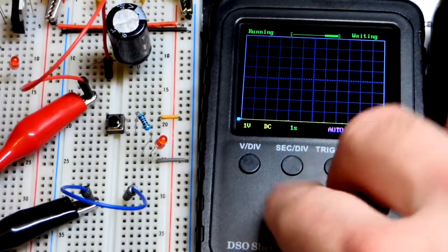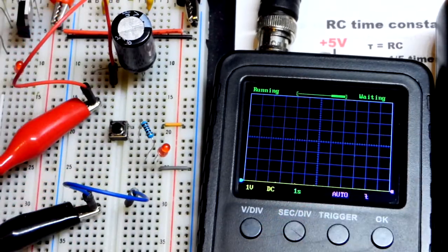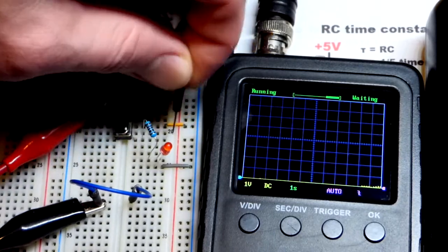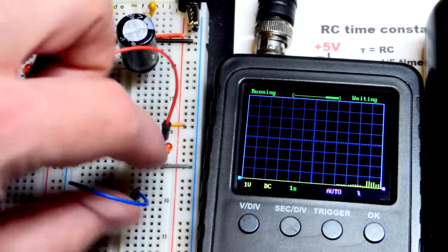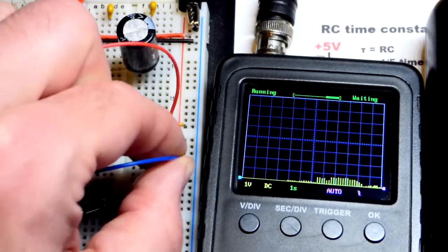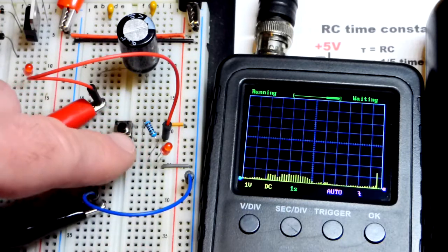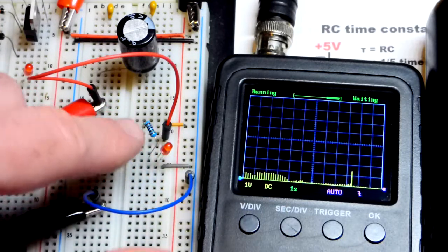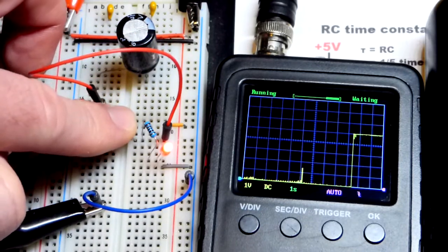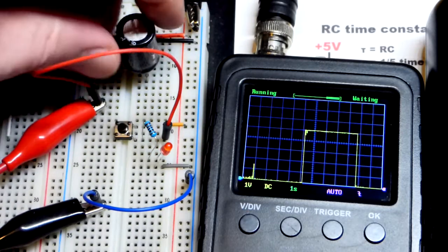I have the cable that comes out of there. There's 2 alligator clips. They're clipped to jumpers that I pegged into the board so that I can easily move them. So I'm going to put that red one next to the resistor, and it's going to look at the voltage in relationship to the negative rail there, ground, the 0 volt reference point. And right now there's nothing because the switch is open. It doesn't see up there until I hit the button, and then it shoots right up to 5 volts. If I let go of the button, it drops right down to 0 volts.